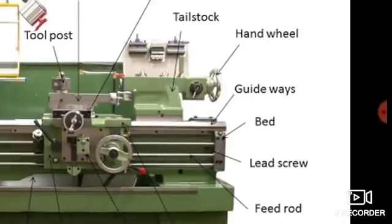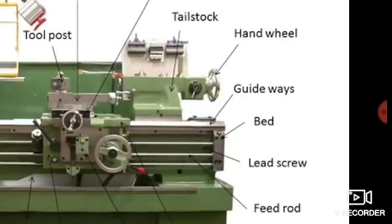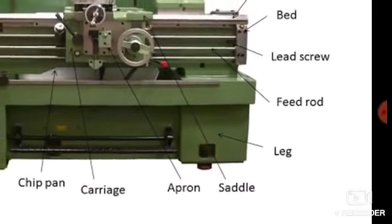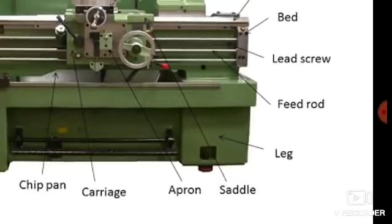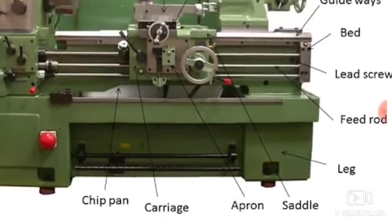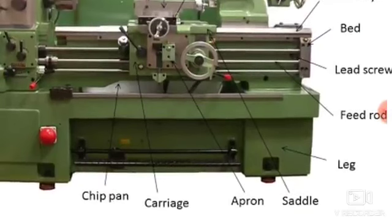Then there is a hand wheel. After that there are guideways. So guideways are basically used for guiding the tailstock. Then the lathe bed is there. Then there is a lead screw. So lead screw is basically used for cutting the threads. So your carriage gets engaged with the lead screw, and then you can cut the thread over the cylindrical object. Then there are legs of the lathe machine. Then there is an apron. After that there is a carriage that can slide over the bed. Then there is a chip pan where you can collect the chip.